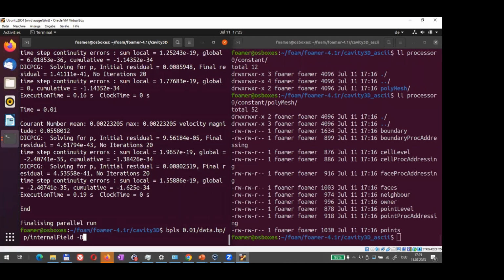We can read it as it is, in this current format. The run may not be as efficient. The decomposition might be bad. I might have some partition with cells all over the place with a lot of processor boundaries. That might happen, but I can still run it.